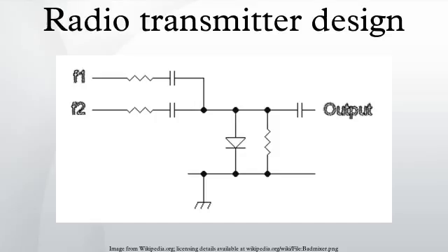RF leakage and shielding. All equipment using RF electronics should be inside a screen-conductive box, and all connections in or out of the box should be filtered to avoid the passage of radio signals. A common and effective method of doing so for wires carrying DC supplies, 50/60 Hz AC connections, audio and control signals is to use a feed-through capacitor, whose job is to short-circuit any RF on the wire to ground. The use of ferrite beads is also common.